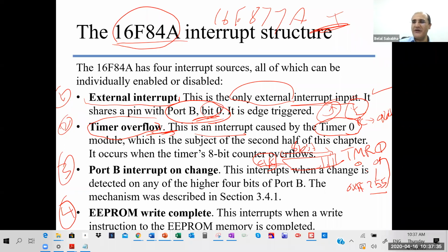Imagine how useful this could be in delays, for example. What we do in delays today, when we did the blinking of the LEDs, the code running on our microcontroller used time-wasting loop delays. We turn on port B and say no operation, no operation, no operation 500,000 times. The CPU is busy, but doing no operation. Then when that's done, we turn off port B.